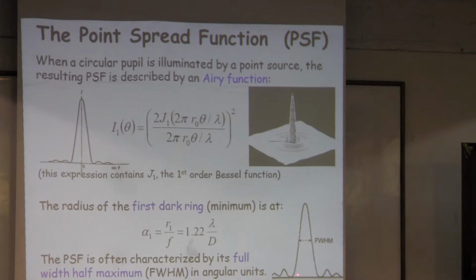That's the part for an optical system that you would like to have critically sampled, maybe even oversampled. So where you put a detector here, you would like to make sure that this part from here to here is covered by at least 2 pixels. Okay? So this is an important equation here, because this tells you about the resolution of your system.